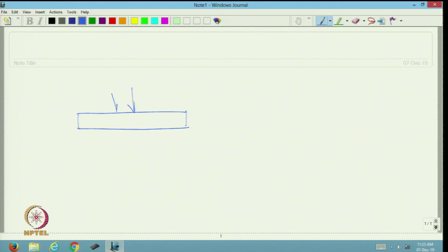this is the flow and this is the thickness of the fabric. So, water is passing through the material from this point to this point, through the thickness. That is why the gradient required is water head divided by thickness here, okay, I say gradient. But in case of in plane the situation is different.